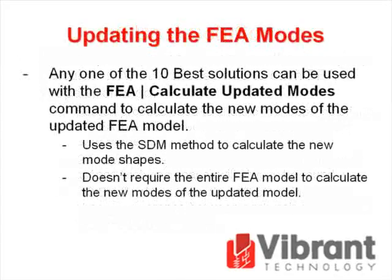Any one of the 10 best solutions can be saved, and the FEA Calculate Updated Modes command can be used to calculate the new modes of the updated FEA model. This command also uses the SDM method to calculate the new mode shapes. It doesn't require the entire FEA model in order to calculate the mode shapes of the updated model.